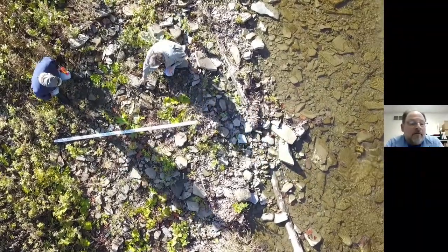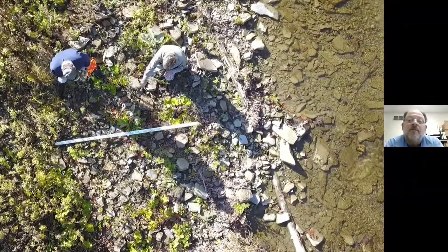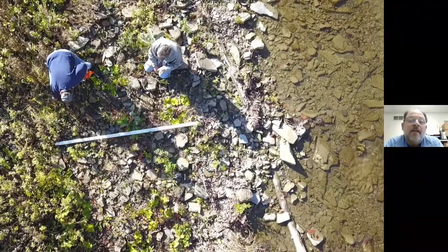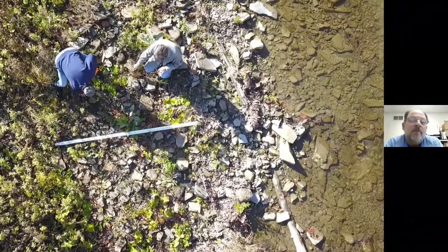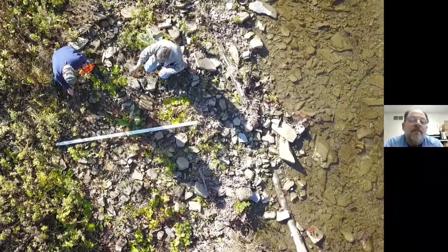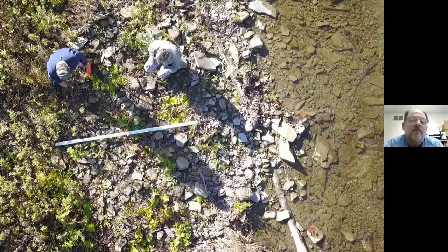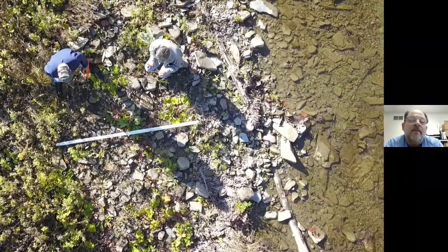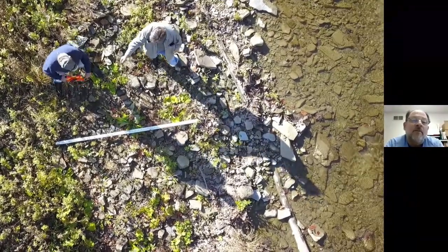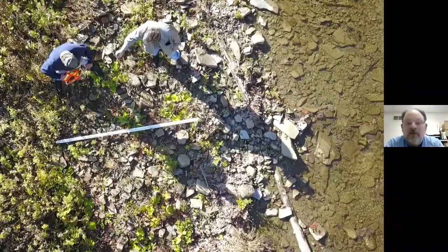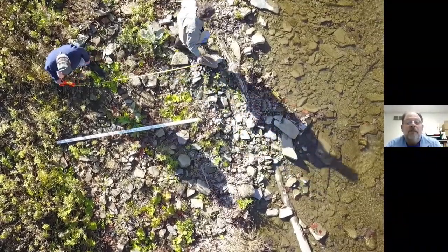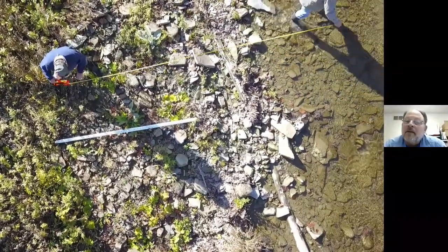So here we are trying to determine where bank full elevation is within this stream channel. Mike's picked up a larger stone there, so we know that's part of the active channel. I'm looking for some indicators where there may be some fine granular material that's depositing, and the vegetation line there at the end of that survey rod is giving me the indication that's about where the channel is activating its floodplain. So we're going to take a tape measure and measure across the stream channel to get that bank full width measurement. And Mike's going to the opposite side of the channel.